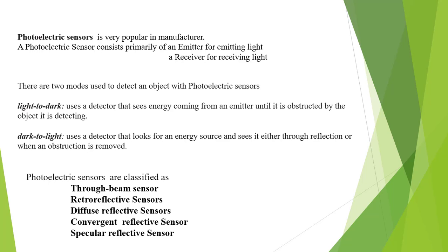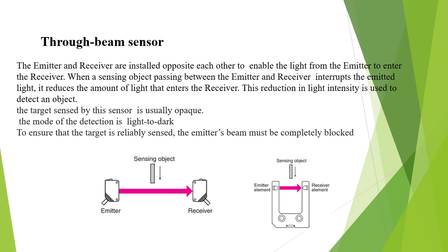Okay. Photoelectric sensors are classified as through beam sensor, retroreflective sensor, diffuse reflective sensor, converging reflective sensor, and specular reflective sensor. First we talk about the through beam sensor.